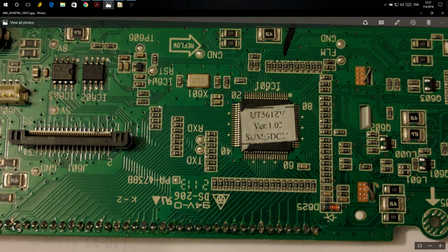As you can see, we've got just tons of jumper links all around here, and I believe this is to facilitate routing more than anything. They're kind of a handy debug tool because I got a pair of tweezers. I can just get in there and grab a hold of it, pull it off. Hot tweezers, for soldering. You just grab the component, pull it off, and then you can measure voltages and just see what happens with things. So I've only pulled a few of them off and stuck them back down. It's no big deal. They don't really do anything. It's just mapping out the pins.